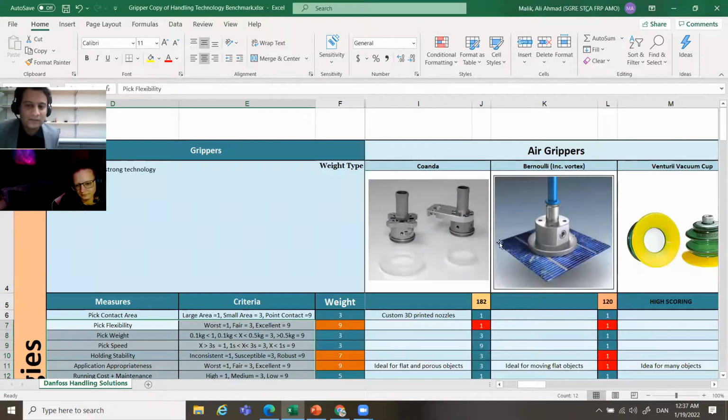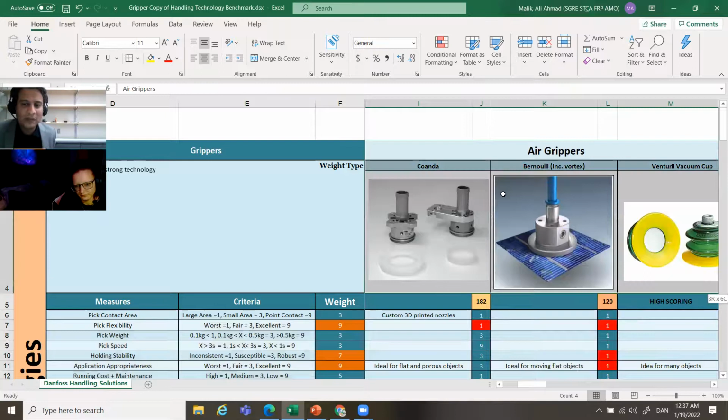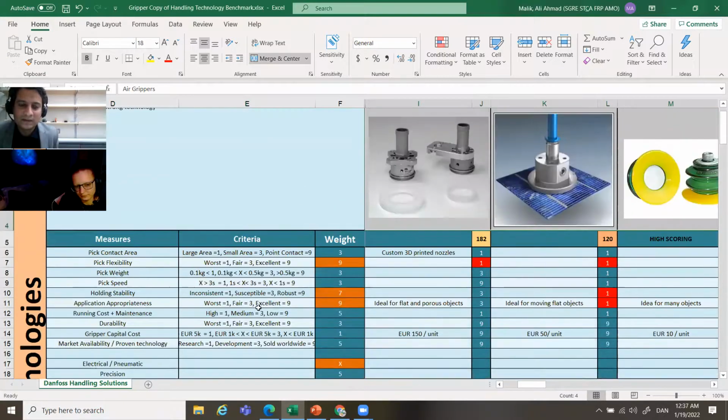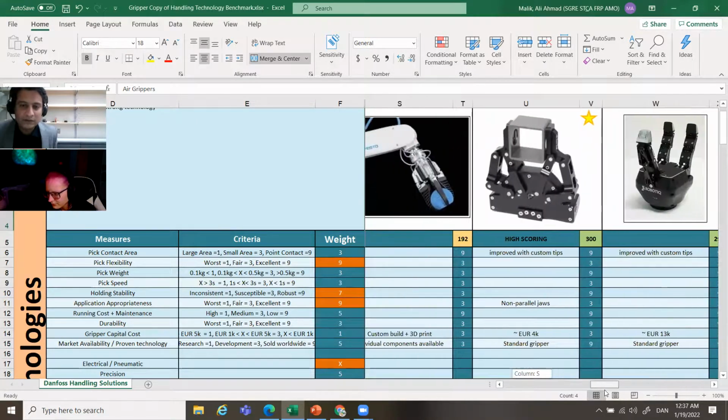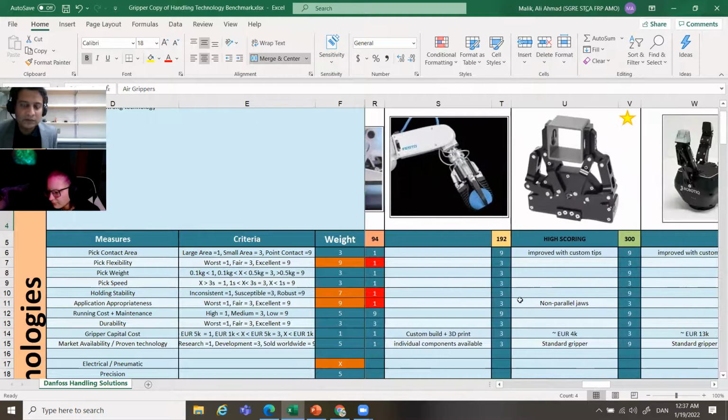So you can really make your own tool and then decide how to select a gripper given the components, and then just play with it. Find different components around you. Just look at your table and find different components, and then decide if you want to pick and place this component with a robot arm, then which type of gripper should you go for? Or if there is any new technology, if there is any new gripper that you should go for.